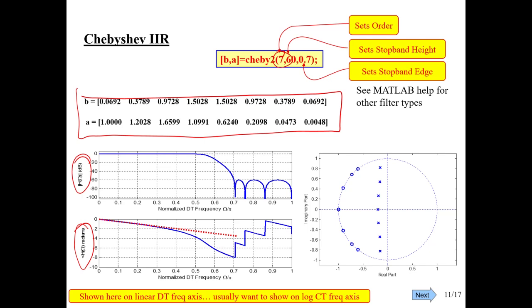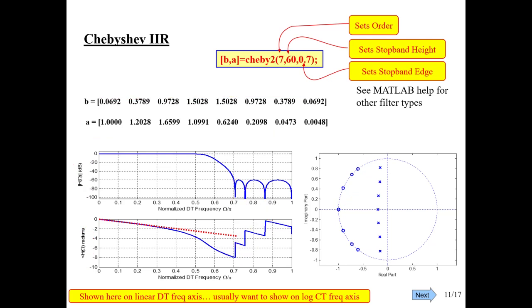You see that you still get some discontinuities in phase when this goes through a 0, right? So we've got a bunch of zeros on the unit circle. So as I'm going from 0 to pi, that's this progression. When I get out past pi over 2 and I get around 0.7 pi, I hit that 0.